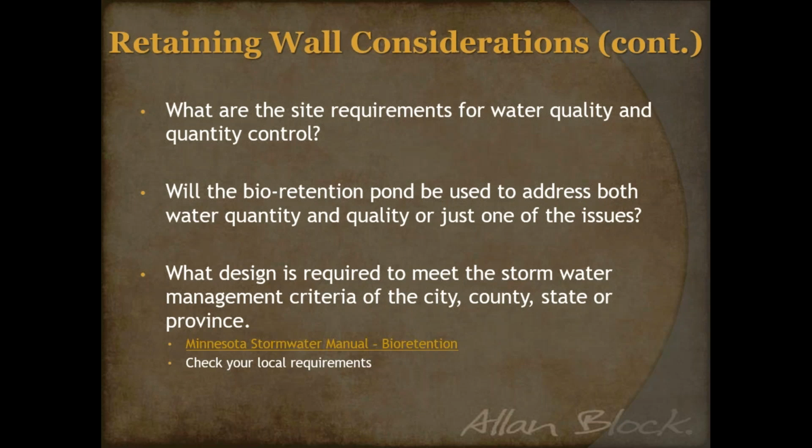For example, the engineer might have to go through the design and handle the first six inches of rainfall over a 24-hour period. So first you've got to calculate what is that rainfall amount and what is that 6-inch volume going to be, because then that's going to have to be stored in some way, shape, or form before I can even start discharging or anything like that. So there are different requirements that you might have to store. There might be different requirements that you might have to get to a contamination level. So is it quality or is it quantity that's going to be controlling your design?